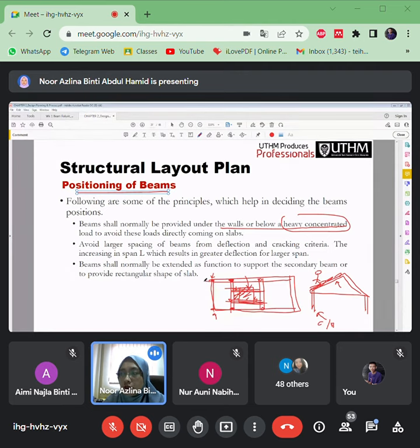Okay, kata dalam architecture drawing dia mention, okay, ini adalah grade A, right? Ni adalah grade B. Dia just lukis water tank je. Dia tak lukis pun kat sini ada, memang tak ada brick and everything. You have to provide the additional grid line. Might be sometimes you have to provide the additional grid lines to show that there will be other structure on that line. Okay, there will be other beams that I propose for that lines. That means there will be additional grid line from you as a structural engineer.